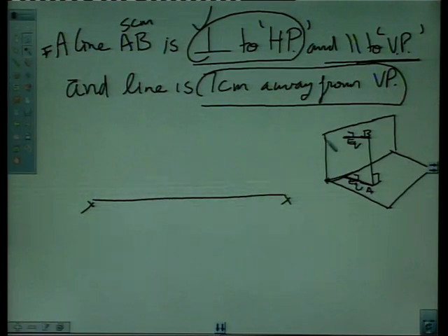Next, now you cannot draw plan first, you should draw elevation first. As in elevation only we will see the complete length of the line AB. This straight line will be clearly visible in this vertical plane. Line AB's projections will be clearly visible in the vertical plane only. So we will draw first a straight line like this, say from here.